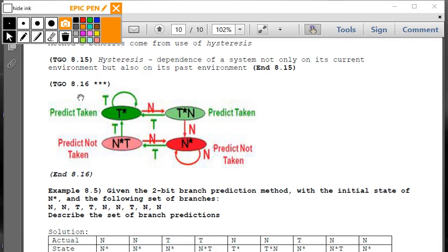So when I ask that question, what are the 2 things that I'm asking for? I'm asking for the ratio between them. This is the one you got right, so mostly right. So it's the ratio of the throughput of pipeline versus the throughput of single cycle, right? And what was the other thing that a lot of you left off that I wanted? When n goes to infinity. Correct. As n goes to infinity, it's going to get closer and closer to the number of stages, which is k.